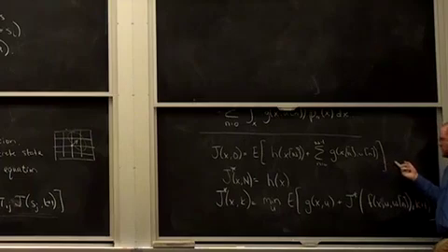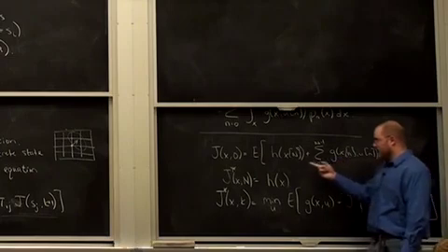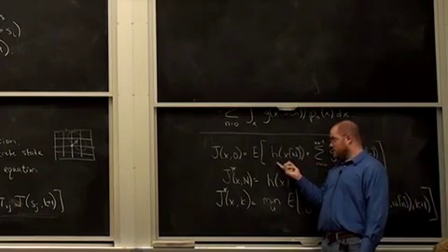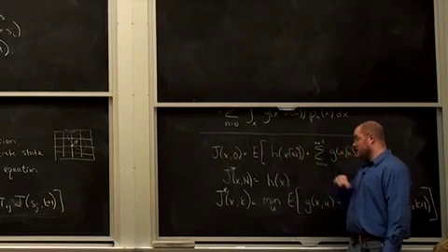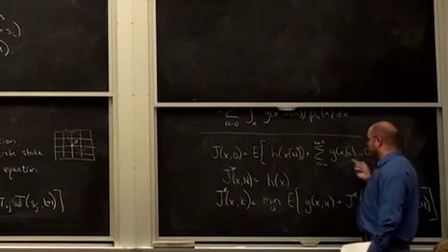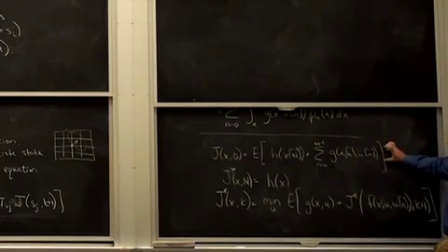We use this in our analytical optimal control too. We use this as the basis to start designing things like our LQR controllers, and we turned it into the HJB. And in the finite time case, we didn't even turn it into the HJB. We can just back this out with dynamic programming. So we can actually use the same thing to analytically try to design some controllers for stochastic optimal control cases.